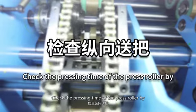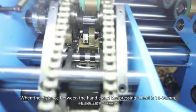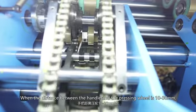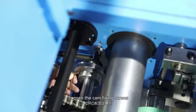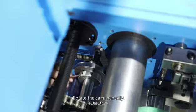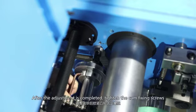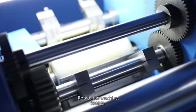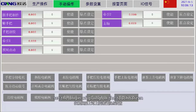Track the pressing time of the press roller by the longitudinal feed handle. When the distance between the handle and pressing wheel is 10 to 30 mm, the pressing wheel is pressed down. If not, please adjust. Loosen the cam fixing screws. Rotate the cam manually. After the adjustment is completed, tighten the cam fixing screws. Set the upper collision point. Rotate the machine. When the gluing board faces the paper roll, set the origin of gluing on the touch screen.